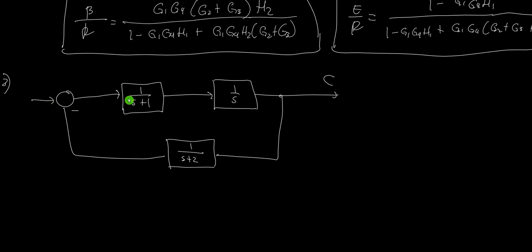It can be a positive feedback, it can be a negative feedback. If this is negative, it's called a negative feedback control system. If it's positive, then it's called a positive feedback control system. And also sometimes you can see a black line here, it's just a straight line. If you see that, this straight line means you can put a transfer function. But the transfer function is just equal to 1. Why? Because the input is the same as the output, because it's just a straight line.